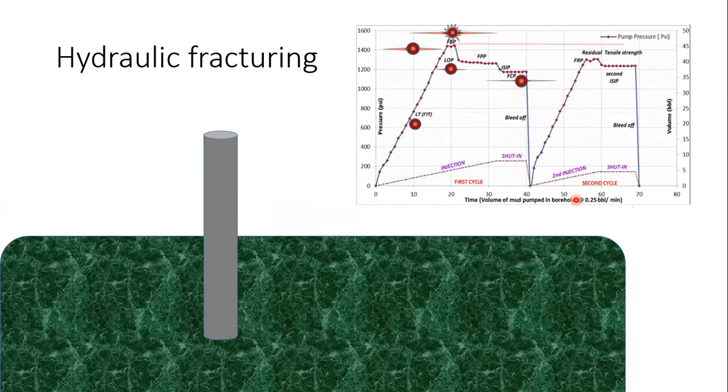If you start injecting fracturing fluids into the reservoir, there is a process to understand how this fracture starts, and this is done through a formation integrity test. You can see there is a graph over here, and this layer is a formation layer. If perforations were done and a channel is generated, we are going to inject fracturing fluids like this, and it will start entering into the channel.